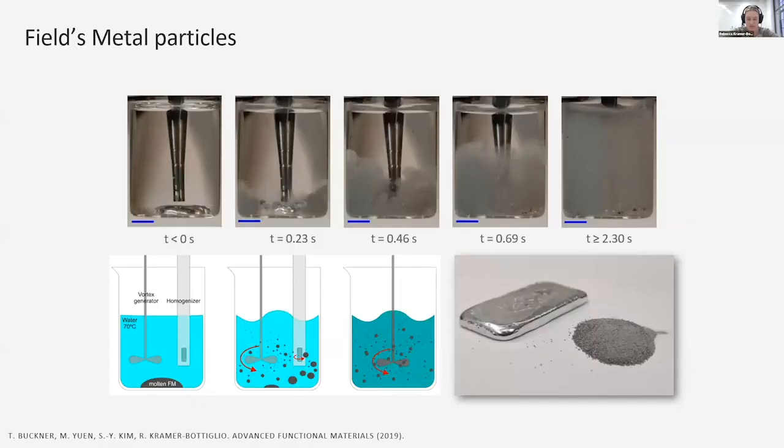So I think it's helpful to understand where we started with this work. When we were first beginning to think about variable stiffness, we started first with thermoplastics, then thermoset polymers, both of which are thermally responsive and change in stiffness via glass transition by about an order of magnitude. But an order of magnitude isn't actually that much, and we were looking for more extreme stiffness changes. So one idea we had is to incorporate phase-changing particles, such as low melting point alloy particles. Then when the material is cool and the particles are solid metal, the material should take on more solid metallic-like properties. And when warm, the particles are melted and the material should be significantly softer since it now contains liquid inclusions.